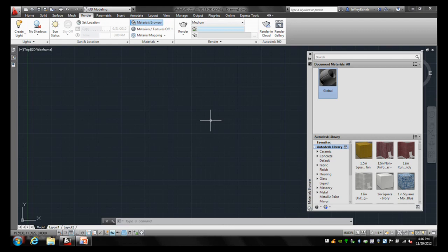So the question was, if I apply the materials, make a block out of the object, and then insert that, will that work? That may. In the past, that was one of the workarounds. I've done that in 2013. The problem I found personally is blocks haven't rendered too well. If you ever explode that block, because you wouldn't be able to edit that, as soon as you explode it, those materials all get messed up.